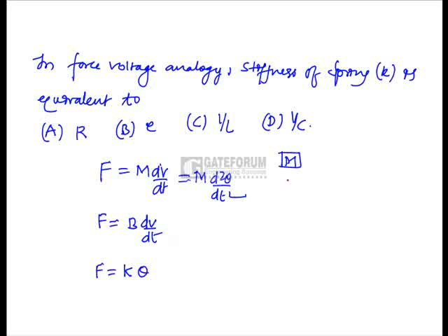Now what he asked is force voltage. There can be two analogies here in control systems, force voltage and force current analogy. This one he has given as force voltage analogy. Many people will think, directly while seeing this question, that spring constant K is equivalent to option A, R, but we have to check it here.